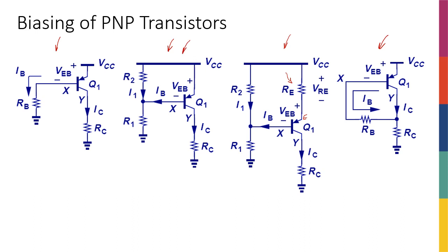This is the circuit with the resistive divider. Remember that this time, for example, if VCC is 2.5 volts and you want a VEB of, let's say, 0.8 volts or 800 millivolts, then the voltage here should be 1.7 volts. So R1 and R2 should be set to get 1.7 volts.